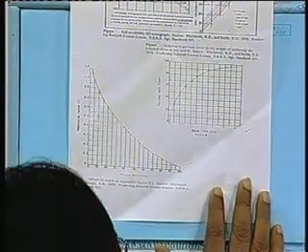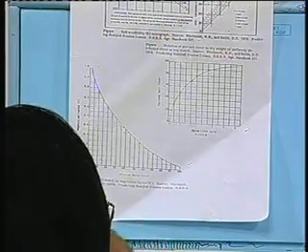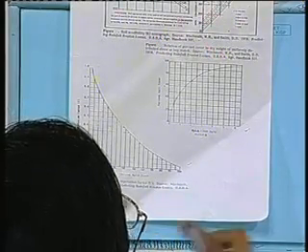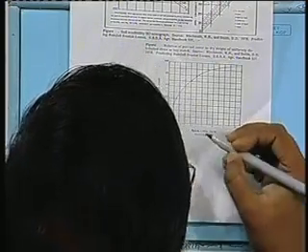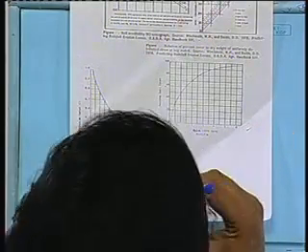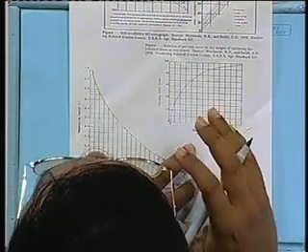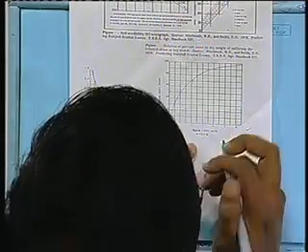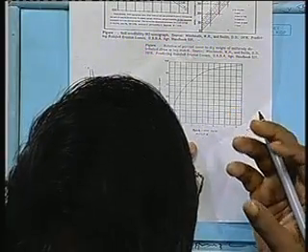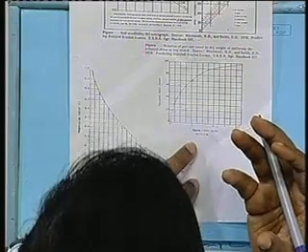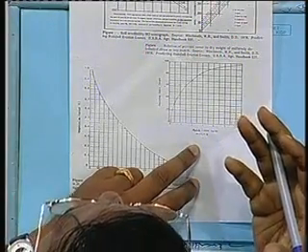If you have brought it out, here itself you can see this. First of all, what is this? The mulch. If you do not remember, the mulch is the vegetative material that is spread on the slope. The mulch is wood cuttings. It can sometimes be raw hay or straw, that is, hay after the paddy is cut. All this stuff would generally be spread onto the soil slope surface.